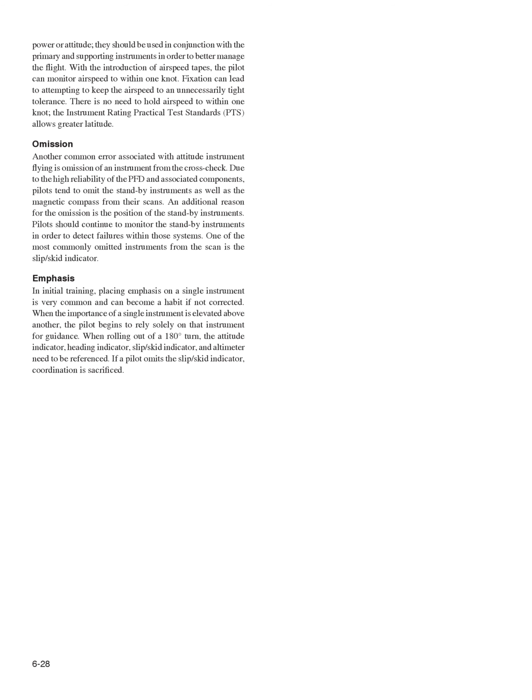the flight. With the introduction of airspeed tapes, the pilot can monitor airspeed to within 1 knot. Fixation can lead to attempting to keep the airspeed to an unnecessarily tight tolerance. There is no need to hold airspeed to within 1 knot. The Instrument Rating Practical Test Standards, PTS, allows greater latitude.